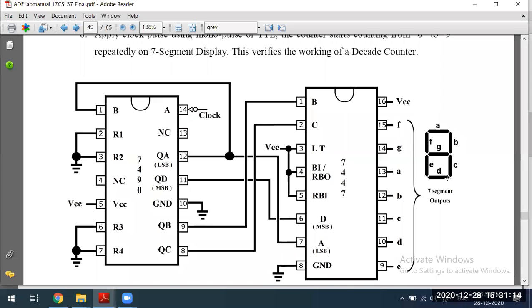Once again it resets and comes to 0, 1, 2, 3, 4, 5, 6, 7, 8, 9. In that way, you will see the output. There is no manual input. Then how will these ICs drive? Because of the clock input. Since there is a 1 hertz clock input, that clock input is going to drive this IC.